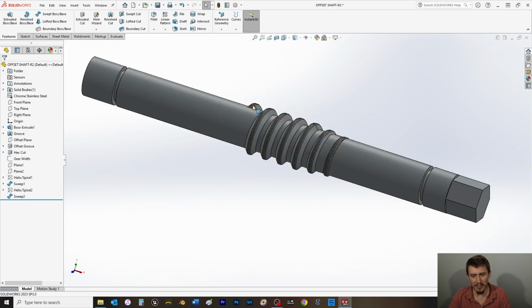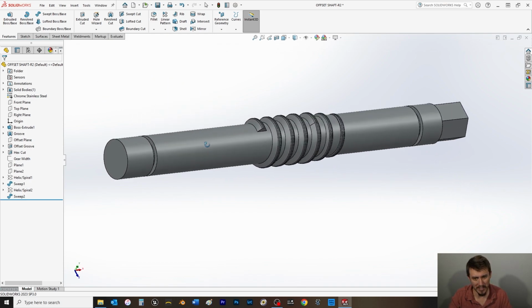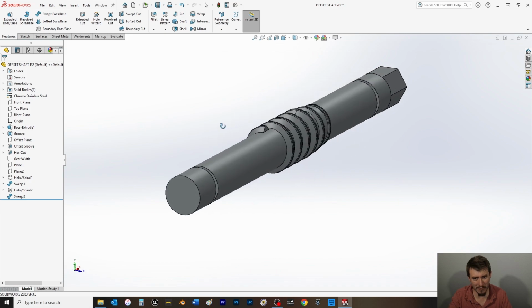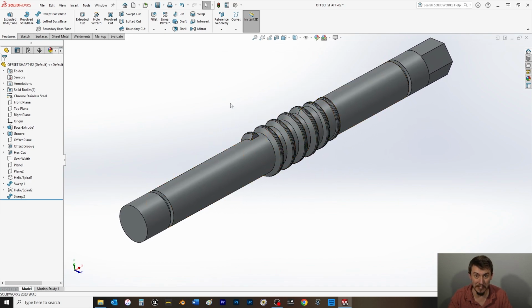And now we need to do it to the same side, so we'll move on to section 15.9 at the middle of page 325. Alright, section 15.9 at the middle of page 325, we're just going to repeat the process on the opposite end here. So I'll rotate the shaft somewhat like this. Again, that was done using the center scroll wheel of the mouse. So then we're going to come over here and make sure first that plane 1 is selected and make it visible again. Don't have to, but again, just for visual reference, it's better to have it on.